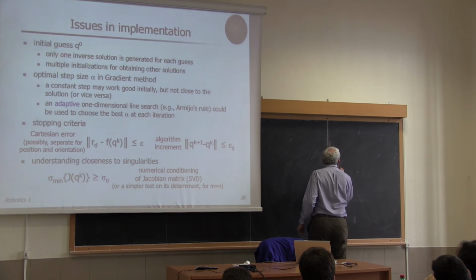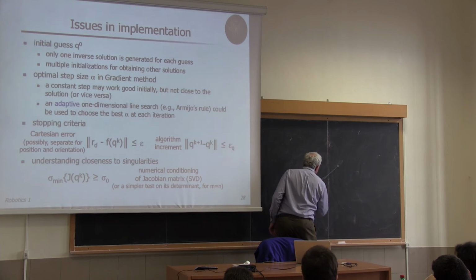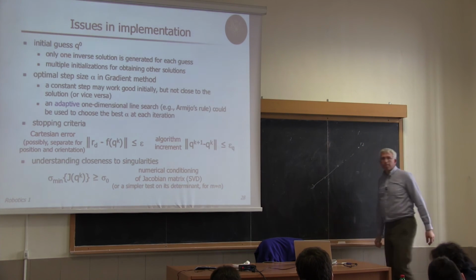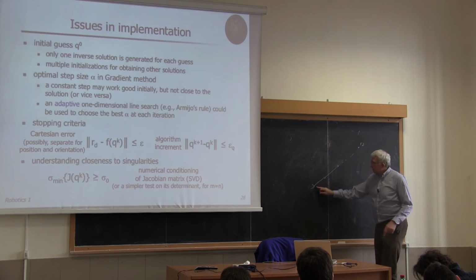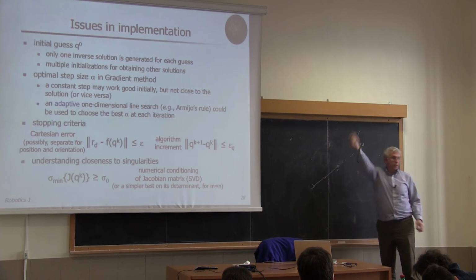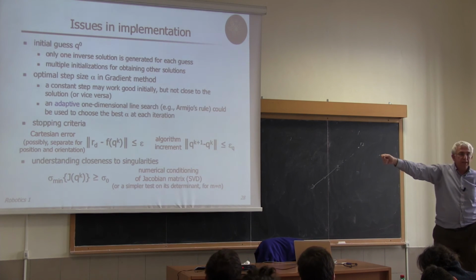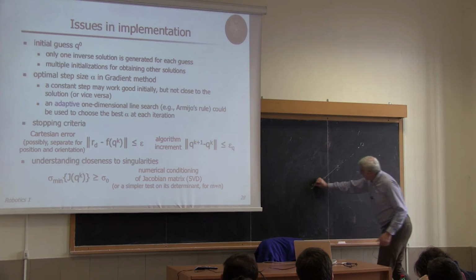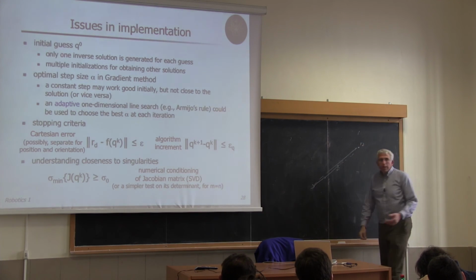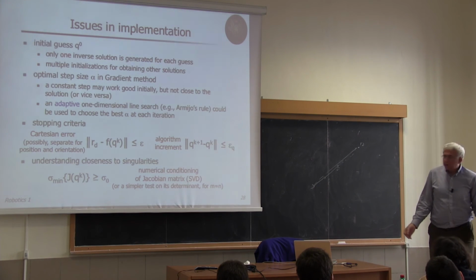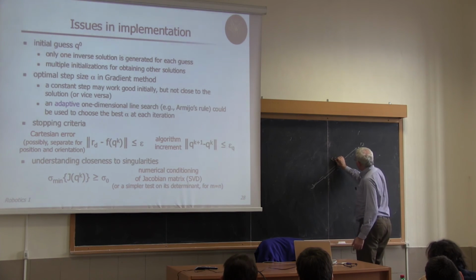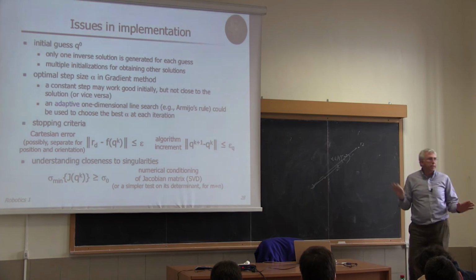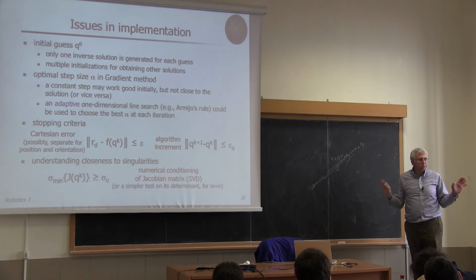So suppose that you are in this configuration, like before, and you should be there. Then the Jacobian is singular here, because it's straight. This is a singular configuration. And the null space is in a specific direction, this one, which is in the null space of J. So let's write here, E is in the null space of J transpose. This is the standard case. Then the system stops. The algorithm stops.